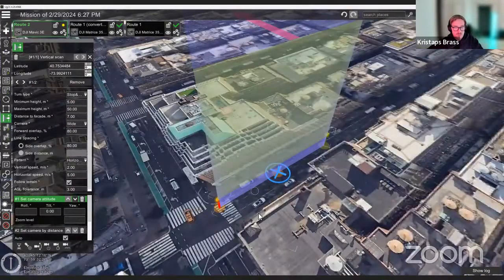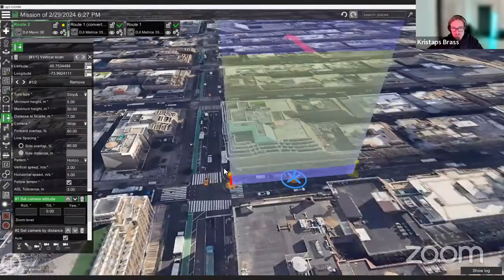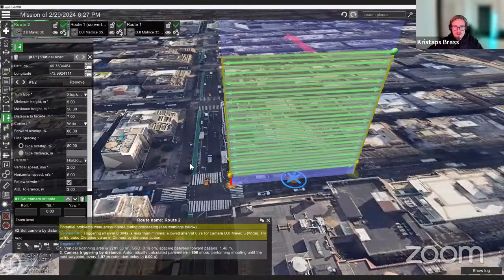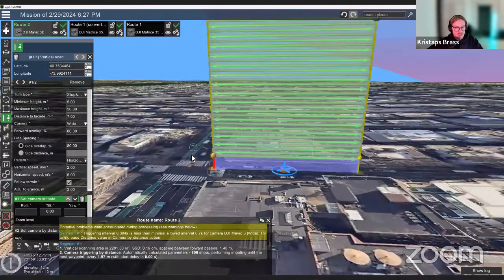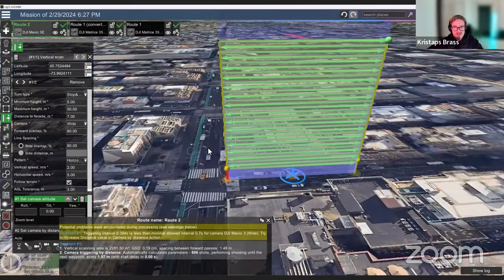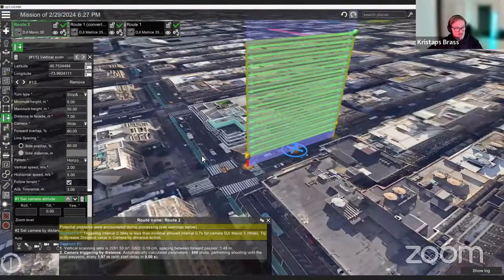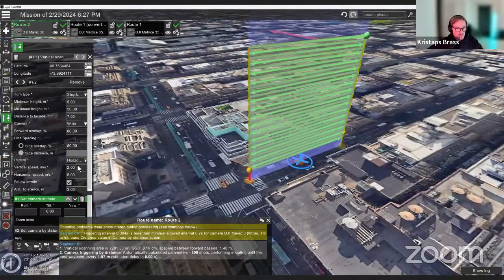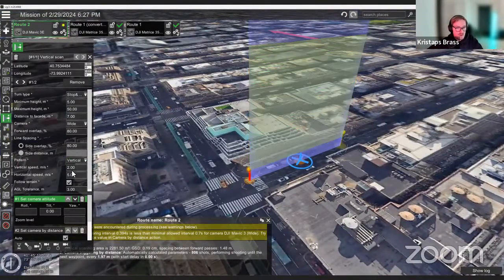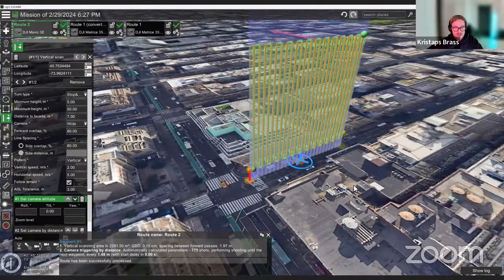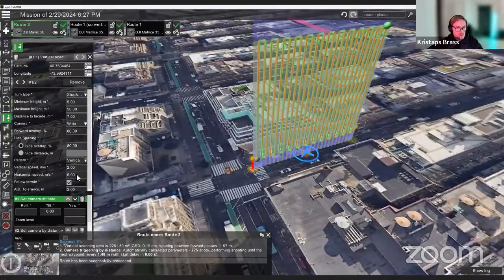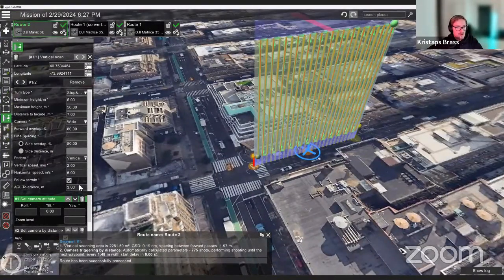In this case, you can probably use both, since it's as tall as long, at least currently looks like. But I think let's go with the vertical pattern. Then the vertical speed, let's set to 2 meters. Horizontal, we can leave as 5.